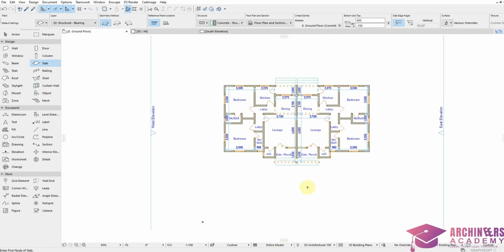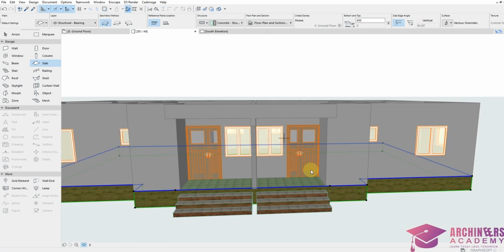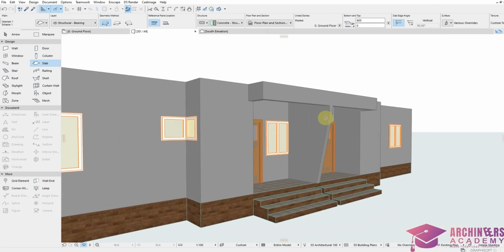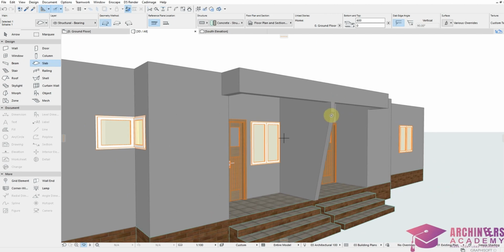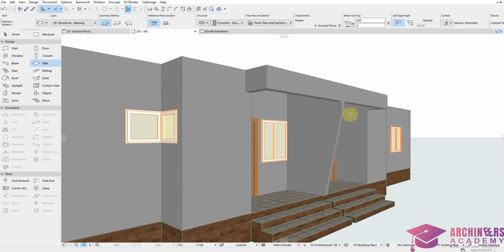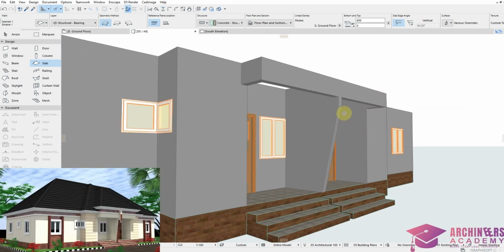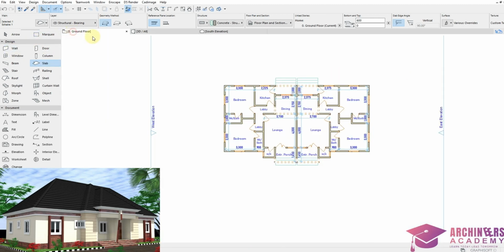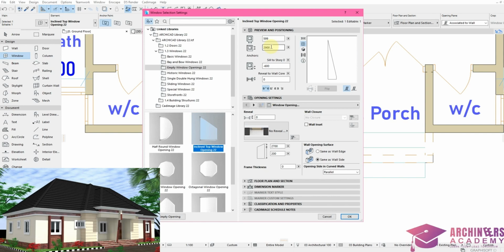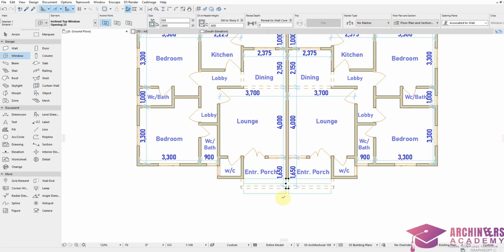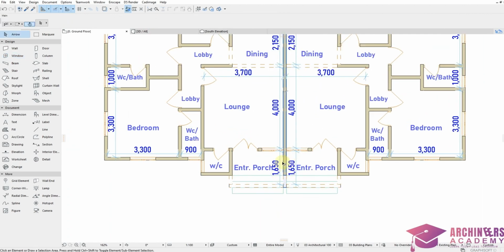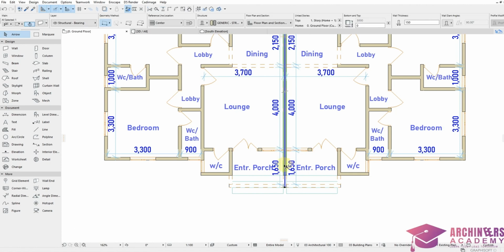Then we can also work on this design properly. Remember this design will make use of empty window opening under inclined windows to place the design perfectly. So let's work on where we missed it. Then we'll come to our ground floor plan. So the problem here is that this wall where this window opening is placed, we have to start from the DPC. This wall right here.